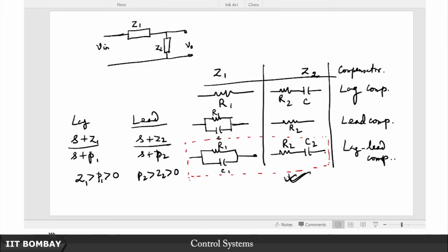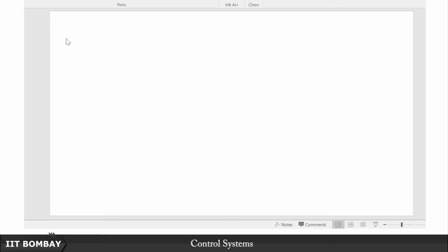In order to bypass this, use is made of an isolating unit. Op amps are very good at isolating because they have infinite input impedance, they prevent loading of the circuit. So if you put a unity gain op amp like this, it might seem like it serves no purpose. What's the use after all? Anyway the voltage gets loaded. But remember, here's the utility of this sort of op amp.